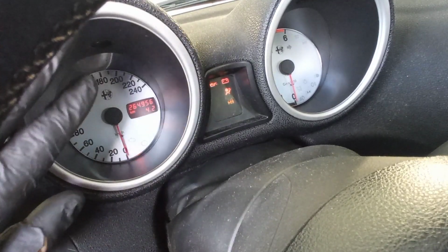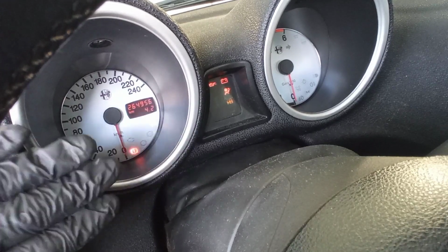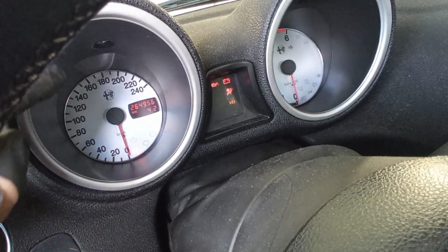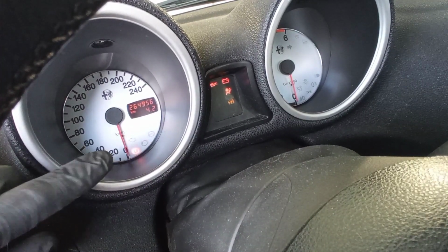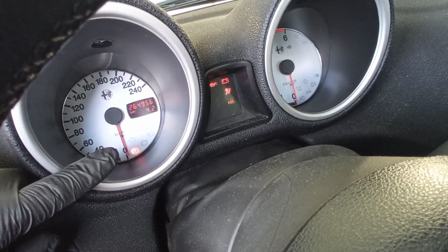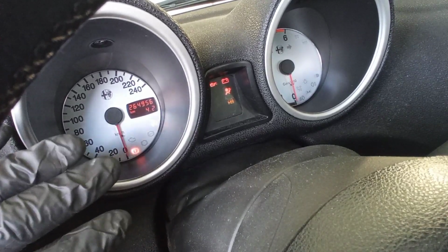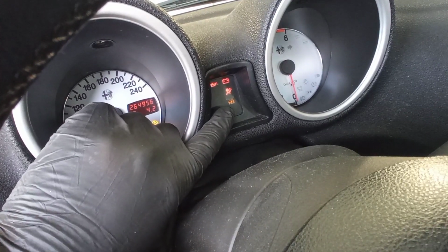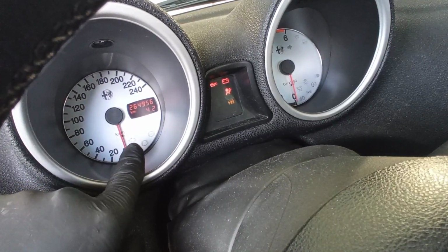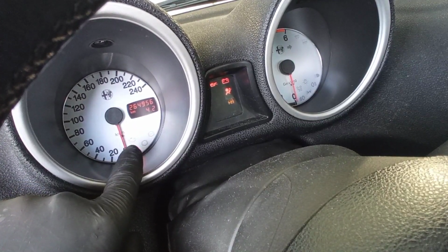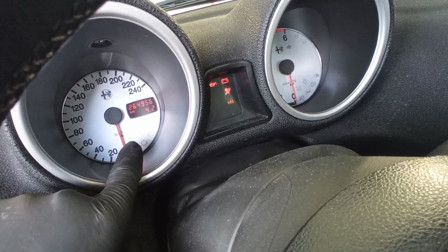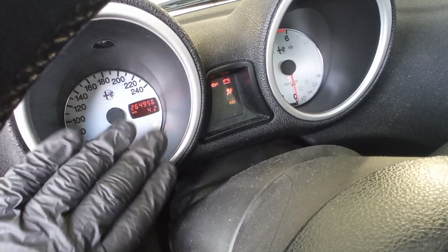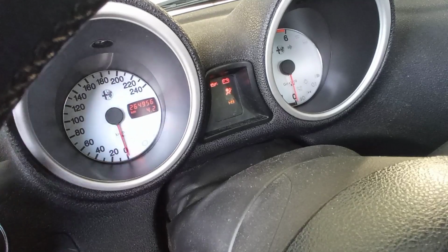If you do a full diagnosis on all of the control units of your car and one of them does not communicate, of course all of the neighbor units will complain that that unit is not communicating. So it will launch a lot of false fault codes about that. Ignore that and try to solve why that unit does not communicate. As soon as you can reestablish communication with the ECU, all those other units will comply and will work out beautifully.